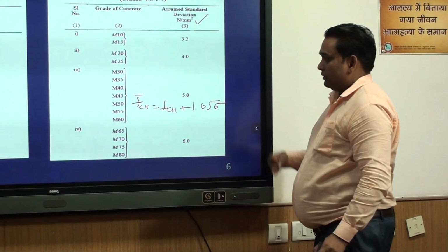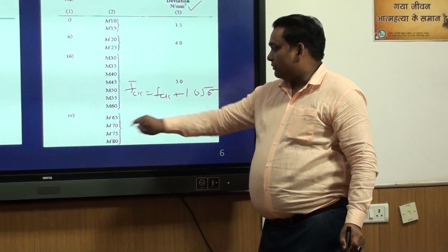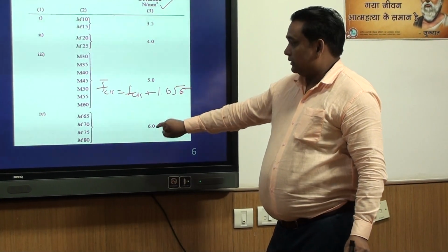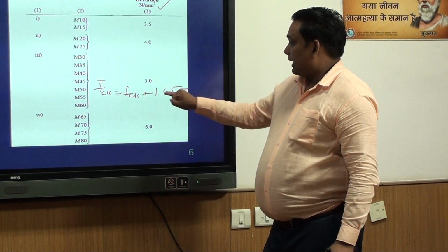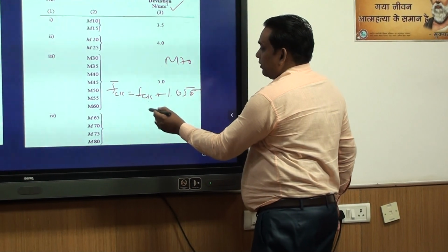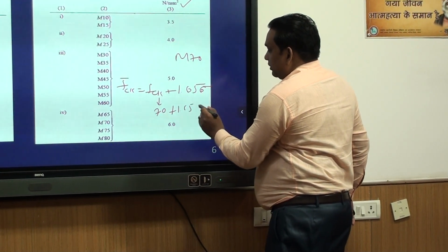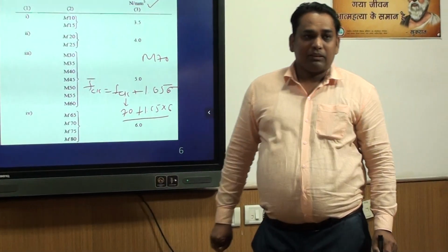Suppose we are discussing high strength concrete, maybe M70. Then we will get the value of sigma as 6. So 6 will be the value, and fck, since it is M70, will be 70. In this way we can calculate the target compressive strength.